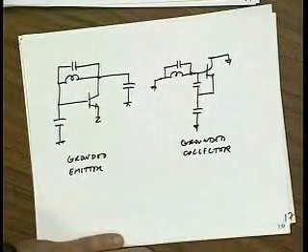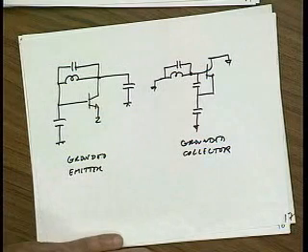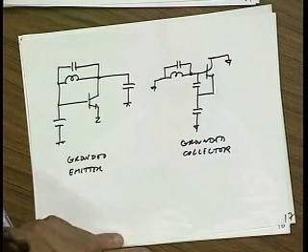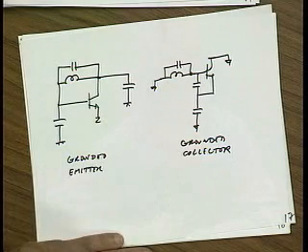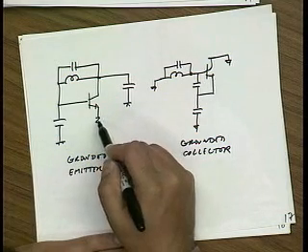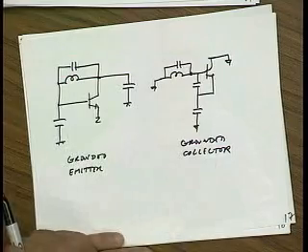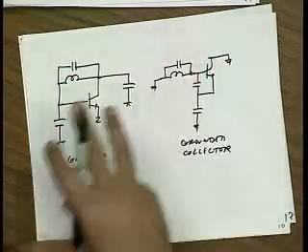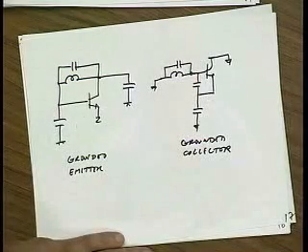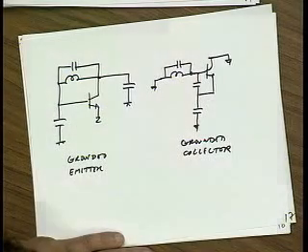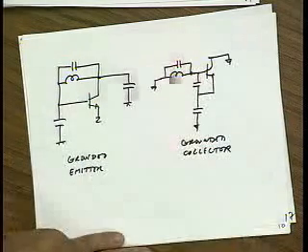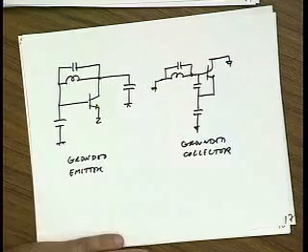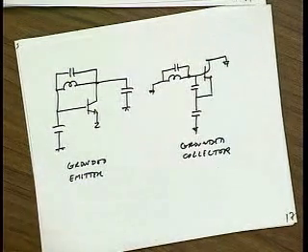So they operate the same? Like there's no difference on loading from the transistor or... No, there is. That's the key point. Because when you ground a node, for instance here, I'm grounding the emitter. So obviously the emitter is not going to load my circuit. So where I place the ground will have a big impact on basically the loading and the feedback factor. But as far as the circuit goes, it's really the same circuit. The emitter points moved around. Okay? What about leakage? What's leakage?